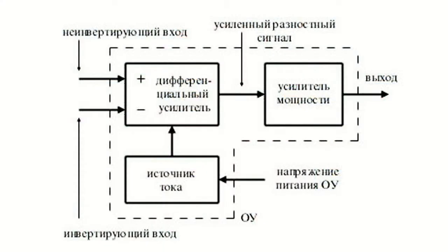If we feed a signal to the inverting input, at the output we'll get the inverted or mirrored signal, i.e. 180 degrees phase shifted. If we feed a signal to a non-inverting input, we'll obtain a phase-continuous signal.